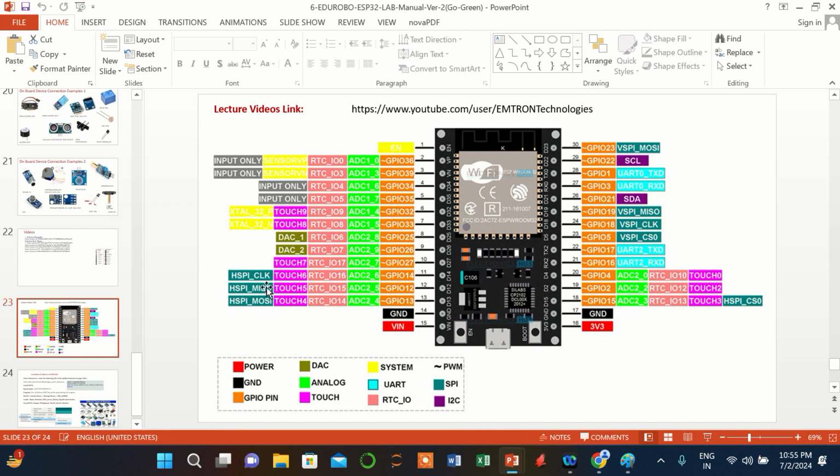Also, these pins have serial ports, right? You can see types of serial communications: MISO, MOSI, CLK, this light blue color, and chip select signal. So these are called SPI ports, Serial Peripheral Interface. But it also has another SPI port. You can see here another gray colored one, MOSI, MISO, clock, chip select. So you have two SPI ports, and also an I2C bus.